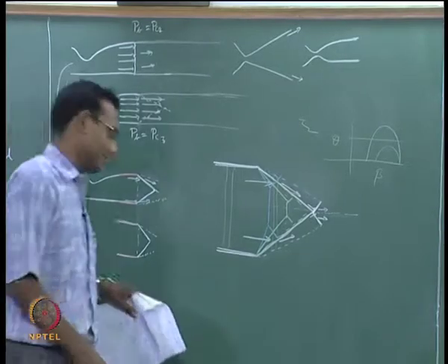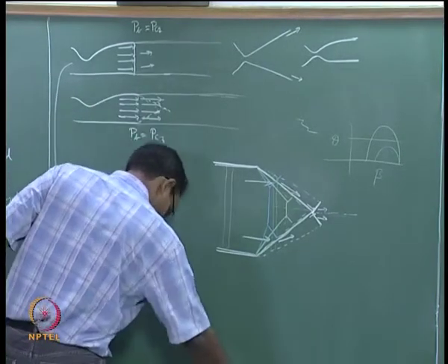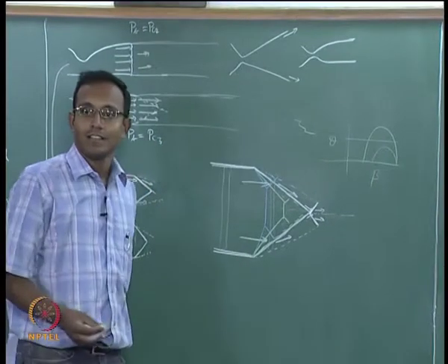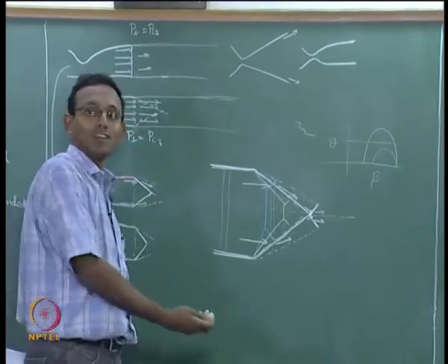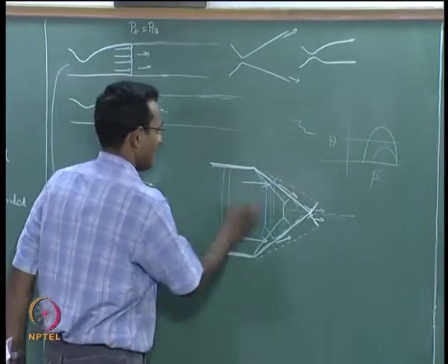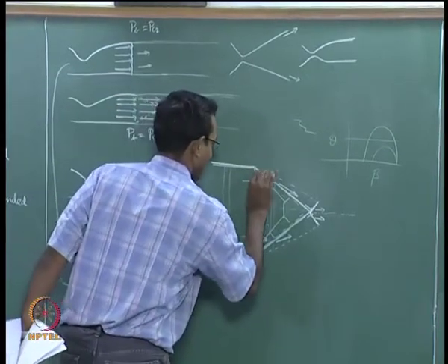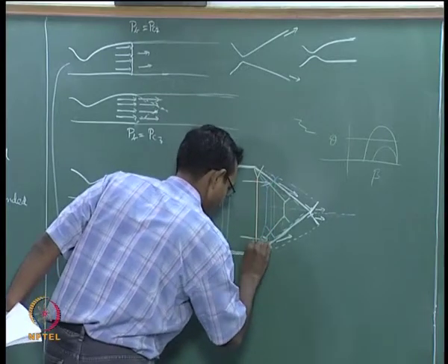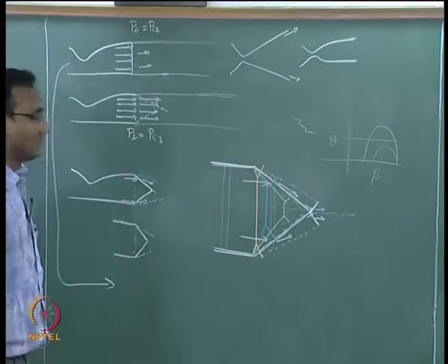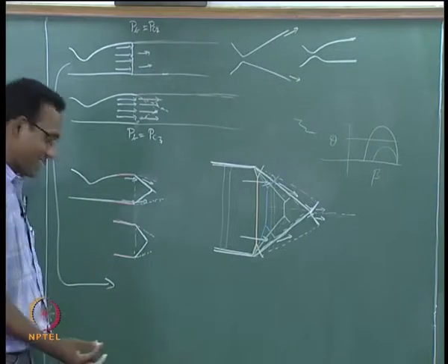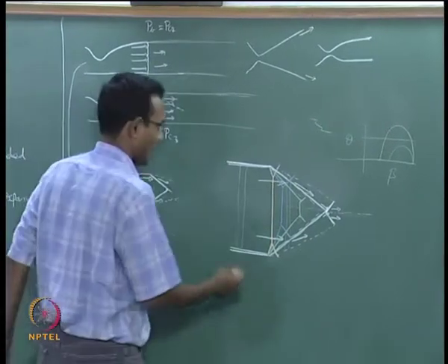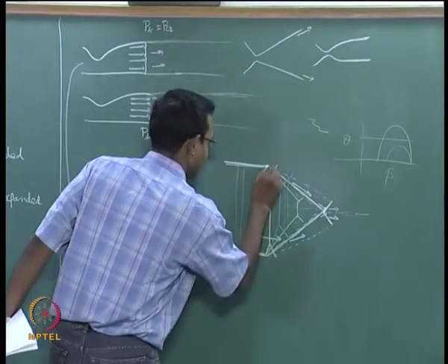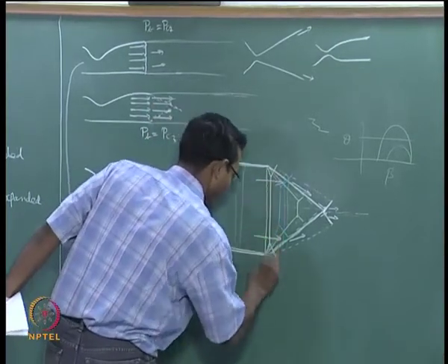Okay, it will look more like this. And if I draw one more slightly higher PB, then I may have this. If I increase any more, let us say I reach my back pressure original PC2, then I will just have one straight shock out here.